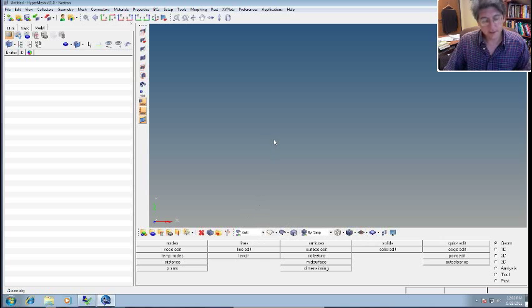It's a little tough to see, but if you want to navigate in the graphical window, if you hit Control and the left mouse button, you can rotate. Control and the middle mouse button allows you to draw little zoom windows. It's a little tough to see how that works now. And then Control and the right mouse button allows you to pan. Again, you can't see it on everything up here, but we'll do that later on. So it's going to be Control and the mouse buttons; the various mouse buttons are what let you dynamically rotate, pan, and zoom. Okay, well, let's get started.